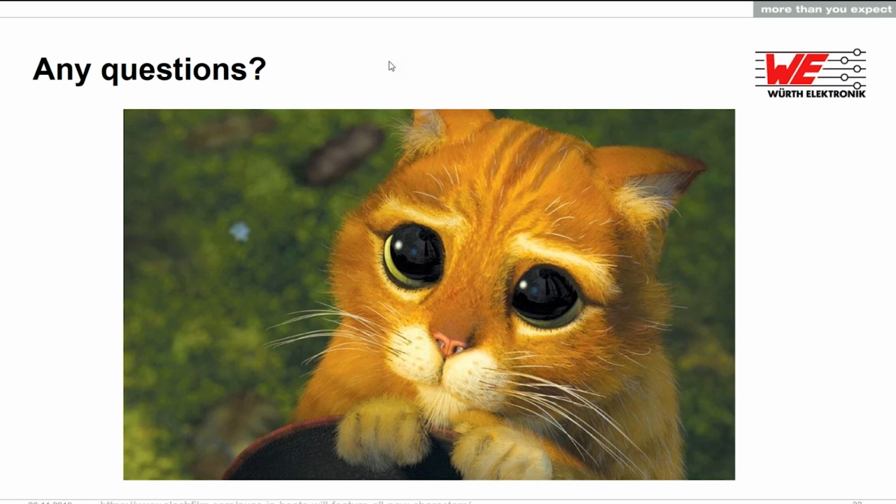So we're going over to the next question. There's someone having a question about the slide with the Curie temperature. Is the effect completely reversible? Okay, so for the Curie temperature, for example, if you're soldering a PCB ferrite onto your PCB and you pass it through a reflow oven, this will definitely go above the Curie temperature. For example, reflow at 260 degrees. When that happens, the ferrite resets.